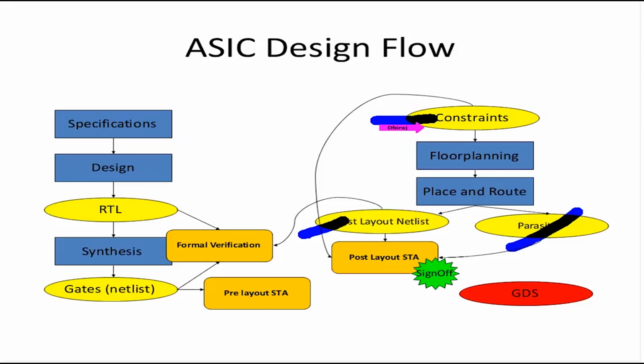But the real violations, the real timing problems will only come after the layout has been done. Hopefully we'll see some examples in the lab. Then we'll do one session with the post layout STA, that is with the parasitics.